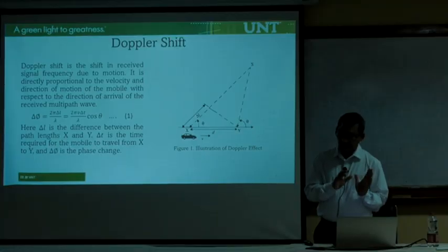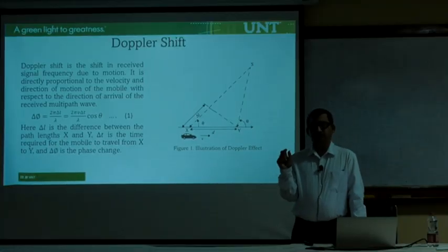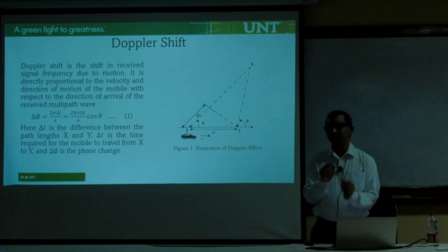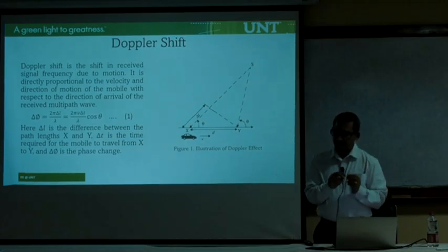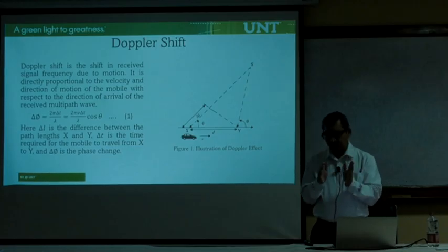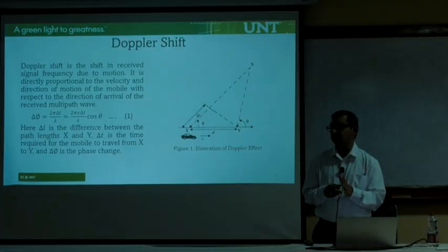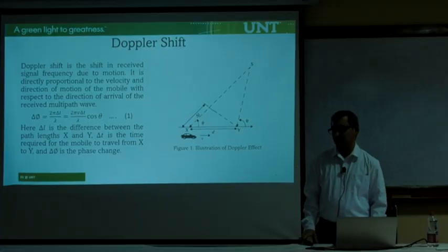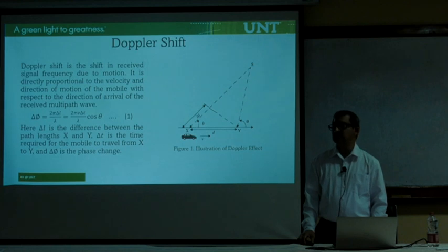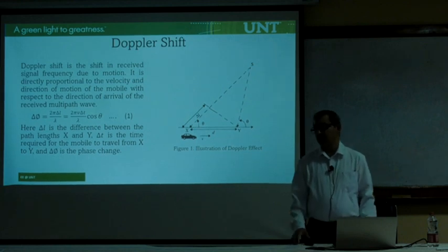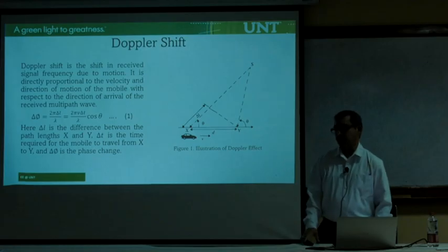But the way they handle this is with something called a cyclic prefix technique. Basically, you are giving some sort of a gap. The cyclic prefix depends on how much Doppler shift you are expecting, but the length of the prefix that we have is not sufficient to handle larger Doppler shifts. If we try to increase the prefix, the data packet will become smaller, and the standard does not allow that at this point. There is a limit on the prefix length, and if you arbitrarily increase it, there are other issues that we encounter.